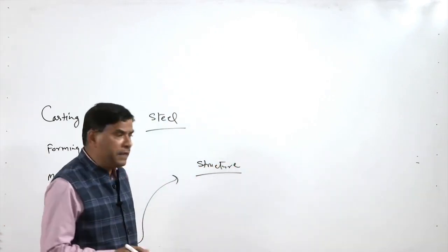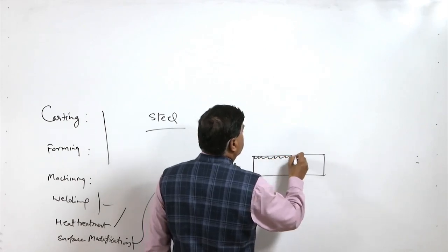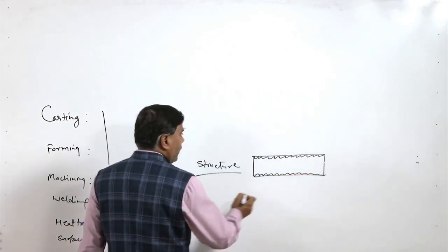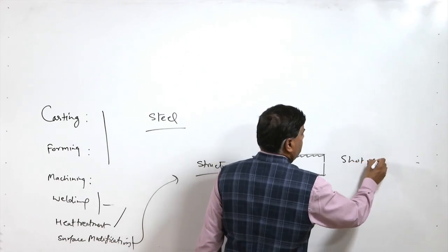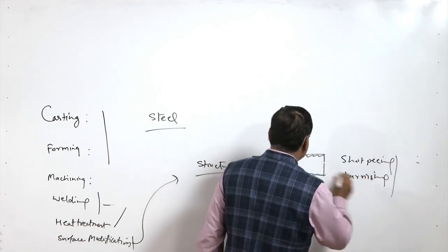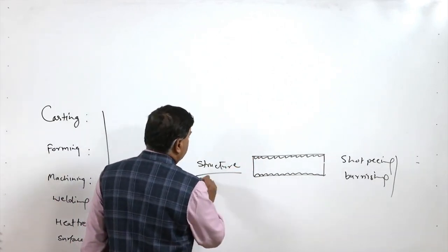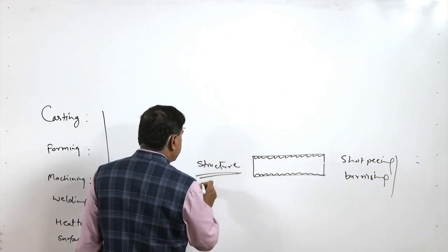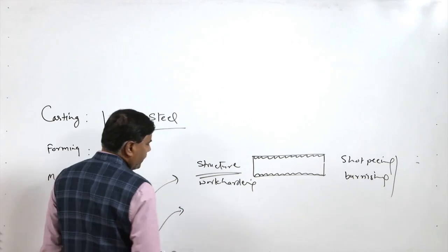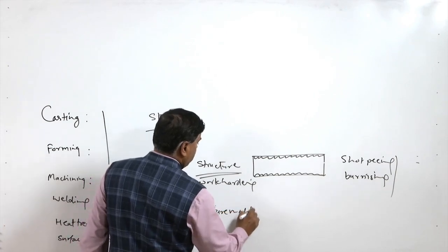Burnishing and shot peening are the examples where controlled, localized surface layer deformation is achieved to enhance the surface properties like hardness, wear resistance, etc. This is based on surface layer structure modification as well as work hardening.